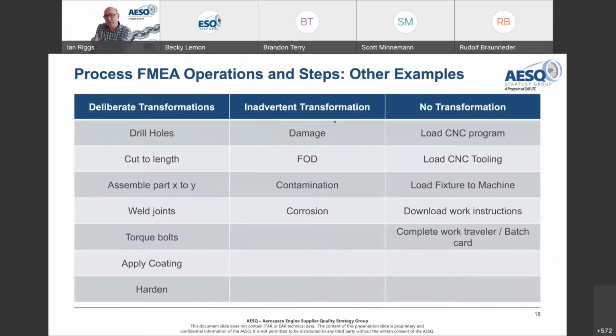The other one where we sometimes get caught up is when it comes to measurement systems. And I've seen two common mistakes we can have around measurement systems. If you take a part and you're creating a number of features, often you see somebody might put down, well, what's the failure mode for this particular hole depth? And so they say, what if your measurement system measures it wrong?